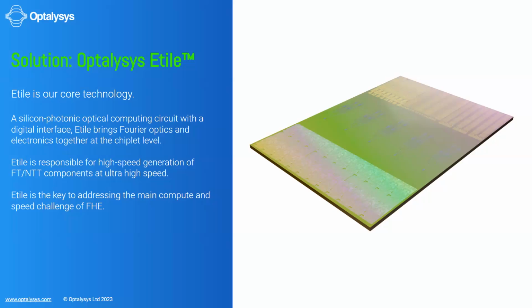So this allows us to have a fully digital wrapper around the optics in our system and to use existing high-speed digital chiplet interfaces to make the most of the speed of photonics. Of course, we actually need to translate digital signals into specific optical signals. So for this, we draw on technologies from the world of high-speed optical communications, both to make use of existing and well-qualified IP, and also because the silicon photonic components developed for this task can manage extremely high information encoding